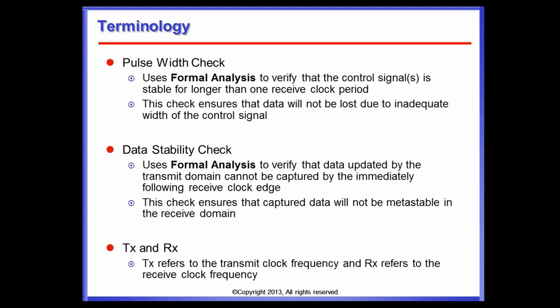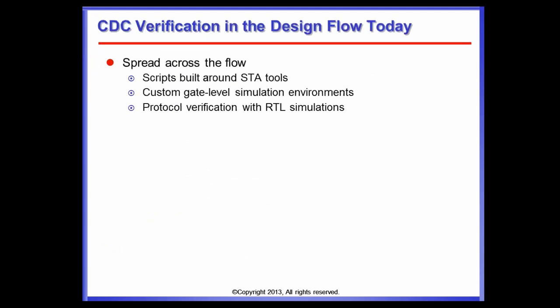So how is this CDC tackled in general? This is for customers who do not use dedicated CDC tools. They build scripts around STA tools to move the edges and see what happens, and try to provoke metastabilities in custom gate level simulation environments to see what the design is doing with this incident. They also verify the protocol, at least of the handshake circuit I showed you before, with an RTL simulation.